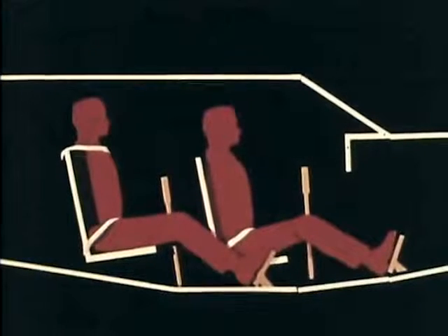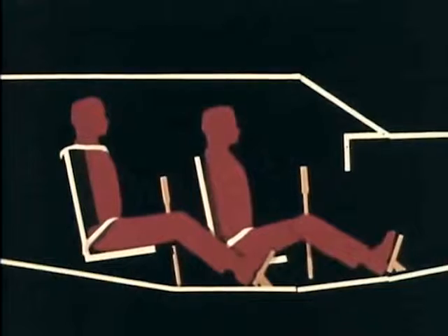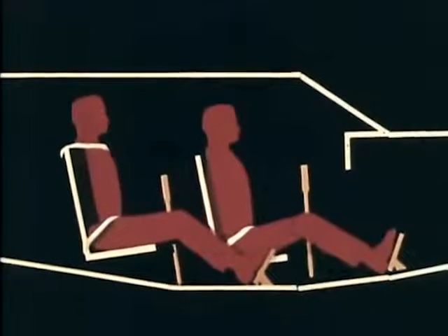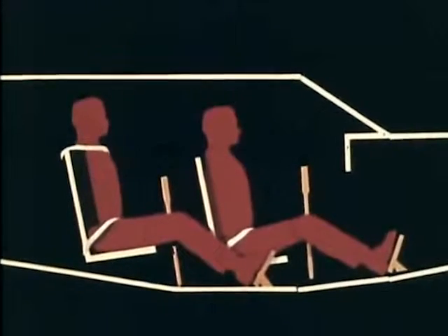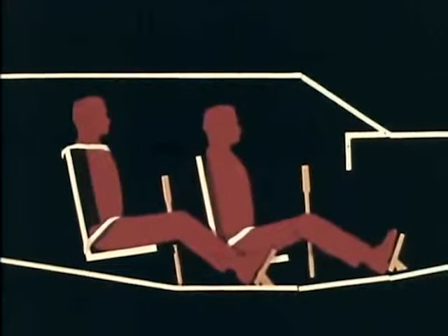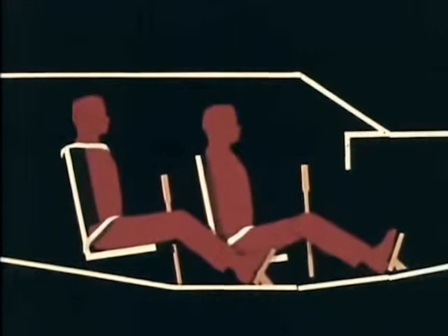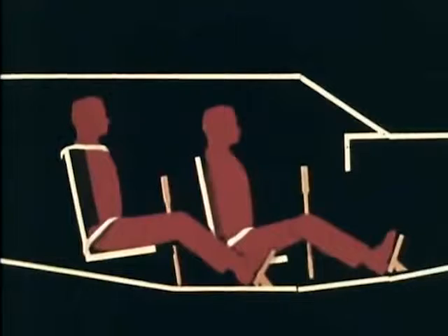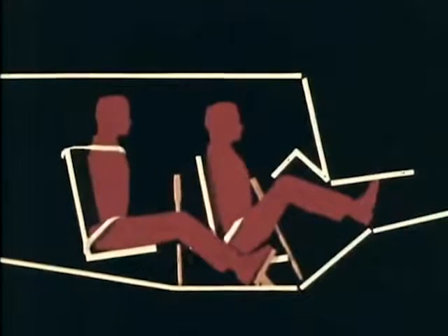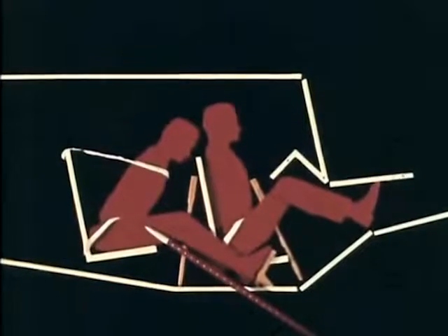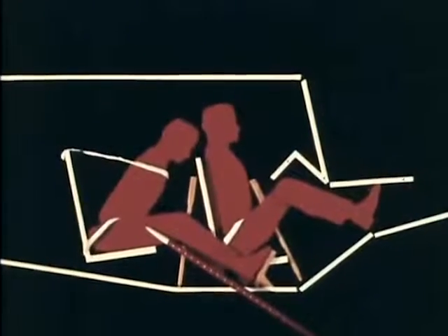If the harness is made of material that stretches excessively, the occupant may still strike objects inside the cockpit. The harness restraining the rear dummy in the 60-mile-per-hour crash stretched sufficiently to allow the dummy's head to strike the back of the dummy in the front seat. This situation was aggravated by the collapse of the structure between the front and rear seats. This moved the front dummy rearward.